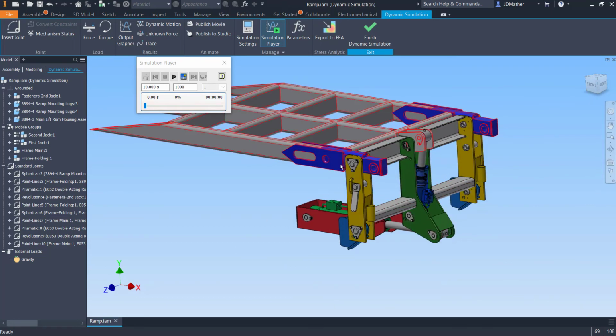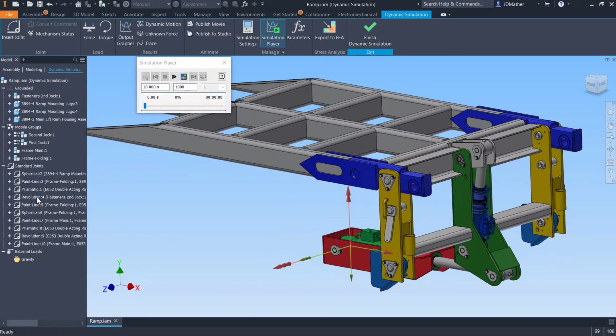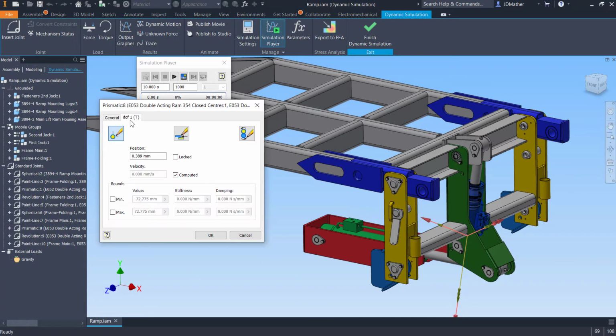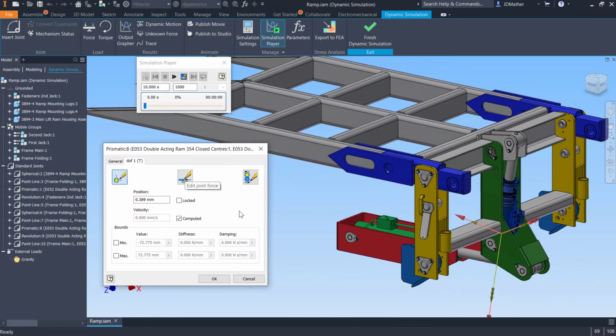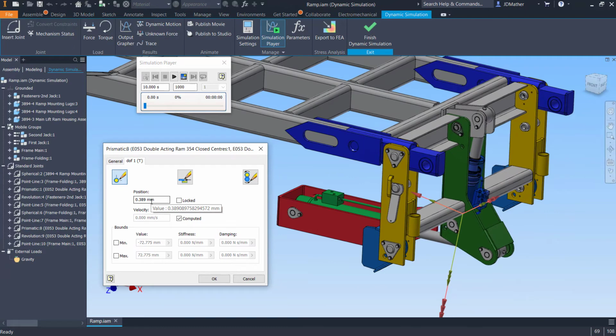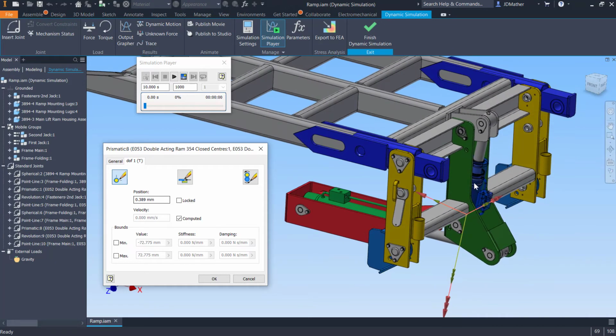So I want to lift this up first. So I'll go to the prismatic joint for this jack cylinder, and I will right click, go to the properties, and I have 1 degree of freedom translation. Earlier when I was doing the measurement, I said I wasn't certain where the origin was at, and here we see that the origin is actually offset a little bit. We're going to ignore that position. It's only a small amount, and in the real world, when we were moving this anyway, we wouldn't be moving it to exact distances, even to the nearest millimeter.